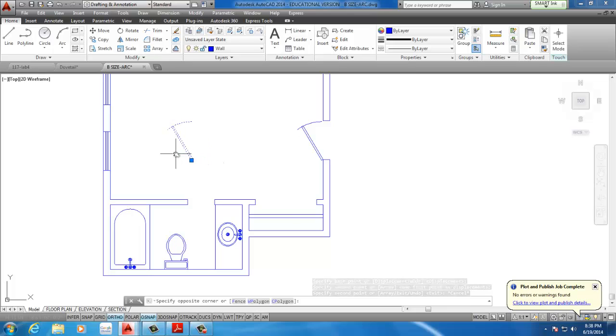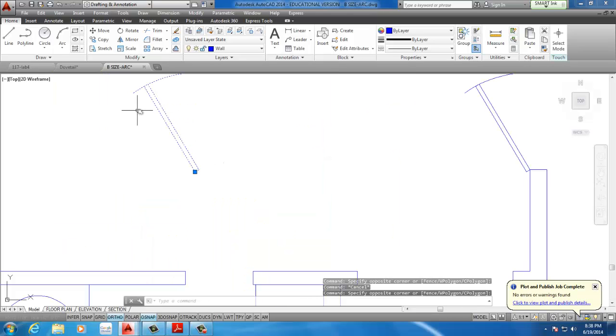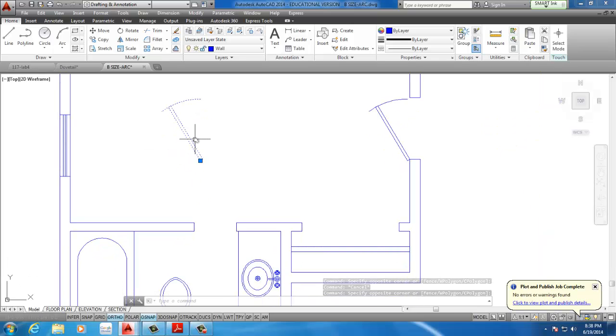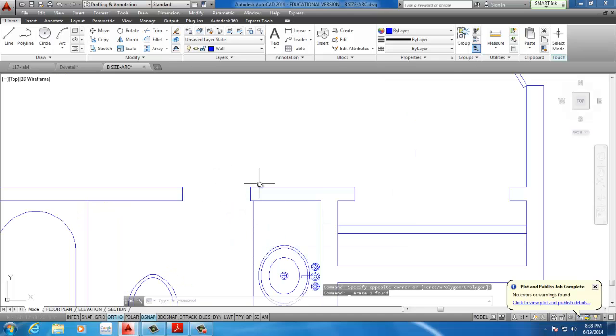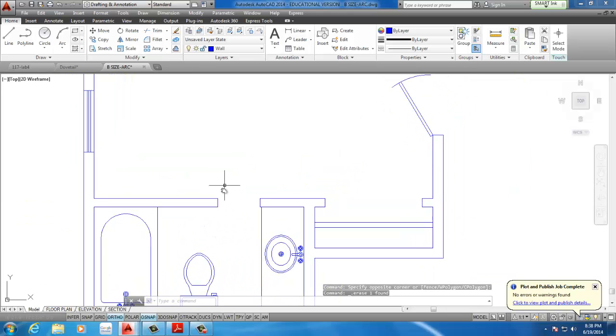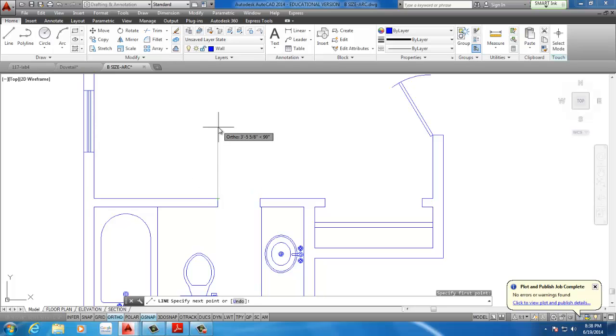Well, actually, technically it wouldn't work scaling down because the door frame itself would get smaller, but the thickness actually never changed. So we'll actually redesign this door. We're going to draw a rectangle going up 24, across 1.5 inches thick, 24, and close it up.